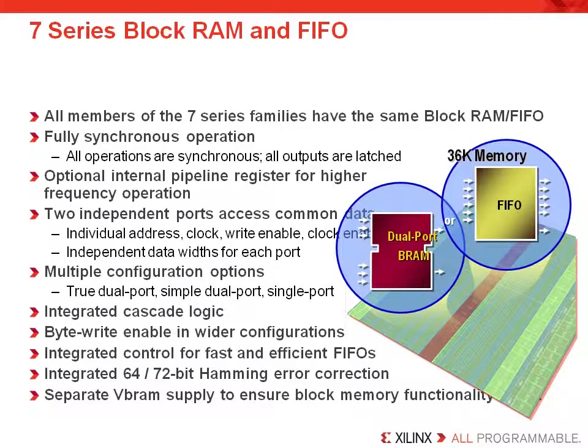Every FPGA design needs some memory resources. Now this is usually accomplished by the use of on-chip block memory, frequently called block RAM. Now the 7 Series block RAM is 36 kbits of true dual-port memory and is frequently used for FIFO construction, large data storage, finite state machines, as well as many other functions. Now the 7 Series devices also include dedicated hardware to convert each block RAM into a FIFO.